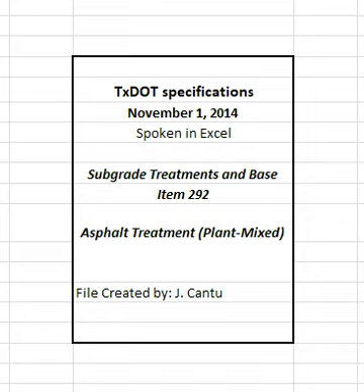4.5.2 Ordinary compaction. Furnish the type, size, and number of rollers required for compaction, as approved or directed. Use at least 1 pneumatic tire roller. Pneumatic tire rollers will provide a minimum of 80 psi ground contact pressure when used for compaction and a minimum of 55 psi ground contact pressure when used for kneading and sealing the surface.